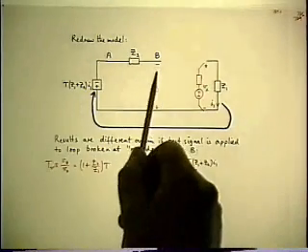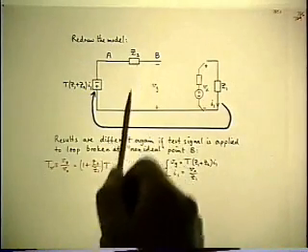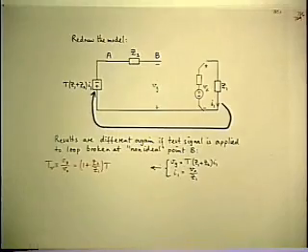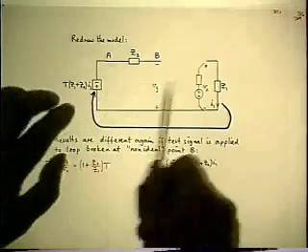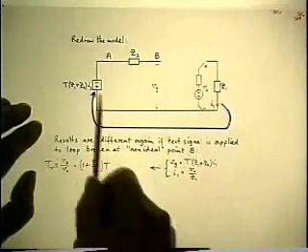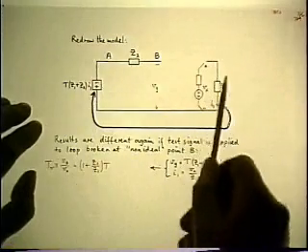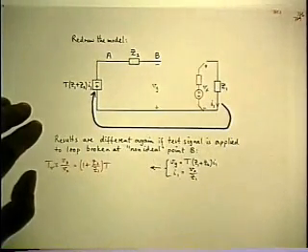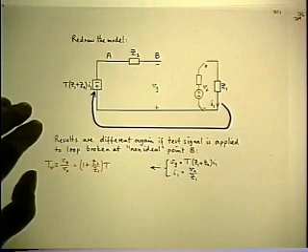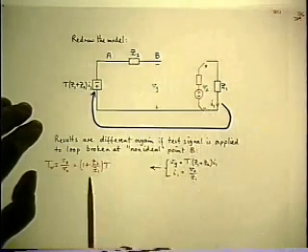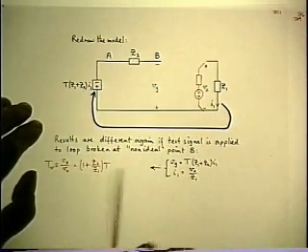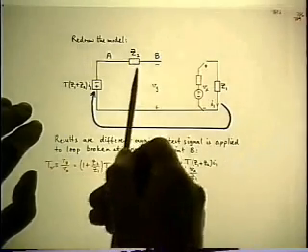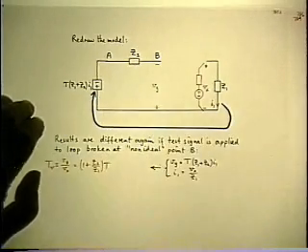So what you've done by breaking the loop is you've eliminated the effect of Z2, but it really belongs in the correct answer because it's part of this divider ratio that gets you from this generator to the signal at this point in the normal closed loop condition. So the interpretation is Z2 does belong in the answer, it's inside T properly, and it's not being properly accounted for if you break the loop at that point.